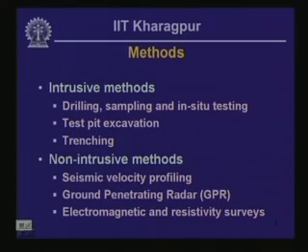And secondly, there could be non-intrusive methods. These methods do not involve insertion of a particular probe in the ground, and we will see the salient features of these methods later on in one of the future presentations. They include seismic velocity profiling, ground penetrating radar and electromagnetic and resistivity surveys.